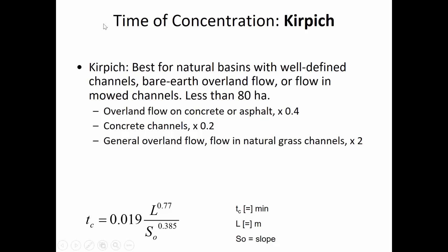And when we're talking about time of concentration, the difference between overland flow on concrete and a concrete channel, the travel time is going to be less in a concrete channel because the speed is higher. So I'm glad you asked that question. There is a difference between these 2 bullet points. Are there other questions?